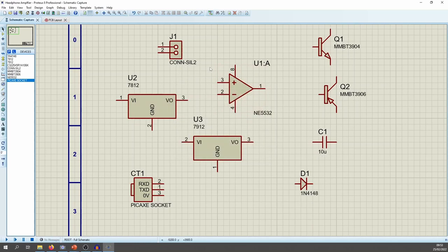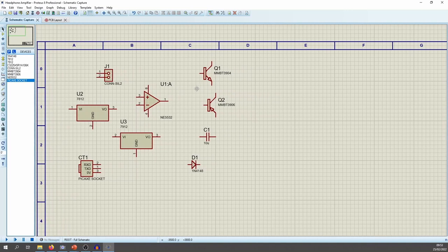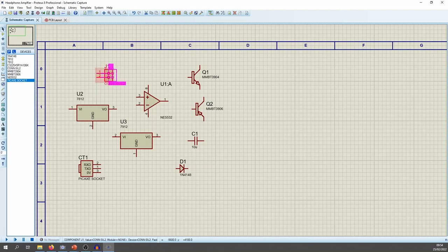Right, so what I'm going to start doing is moving components that we've completed over to the right hand side, so we know which ones are done. So the Consil 2, I'm only using that as a feature on the PCB to connect one of those 9-volt battery headers. You know the 9-volt batteries that have got the clippy header thing. When they come off with two wires, I'm just going to use that to solder onto the board. So there's no component to buy for it. It's just a PCB feature. So we're done for that part. Easy.